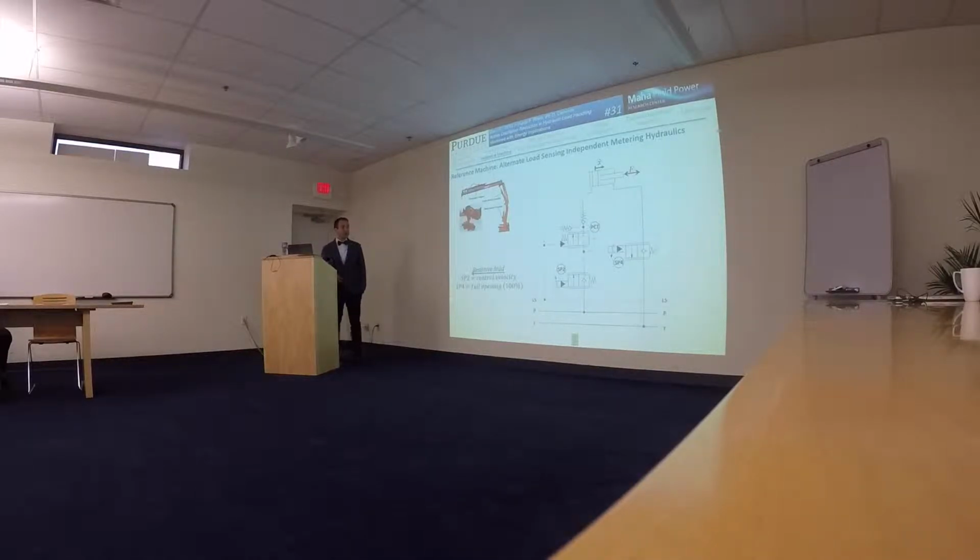And here the challenge is that the load conditions can be different on the machine, and so depending on the load condition, the inputs to the 2 valves have to change. So in the case of a resistive load where the force of the load is in the opposite direction of the motion, we don't need to basically control this one. So we can just fully open SP4 and partially or fully, we can control SP2 in order to control the